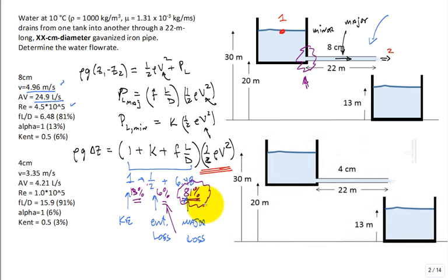How would you do it? Well, you would increase the diameter of the pipe, something like that, because the flow rate's very sensitive to the diameter of the pipe. Rerun that problem. Pick a smaller diameter pipe, 4 centimeter diameter pipe. Well, if we were getting 25 liters per second, I cut the diameter in half, what should I get, 12 liters per second? No, it drops down to 4 liters per second. It's a significant drop or reduction. Why? Well, the velocity went down. That's understandable. But the area went down. Okay, so you have a lot lower flow rate.